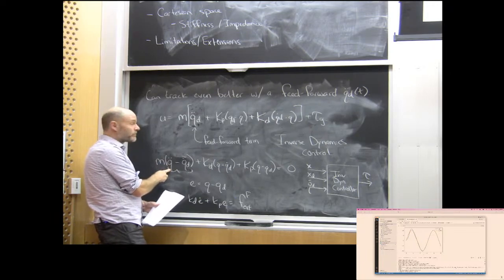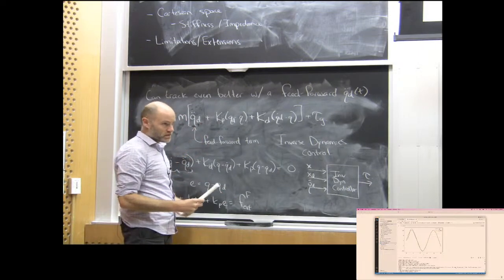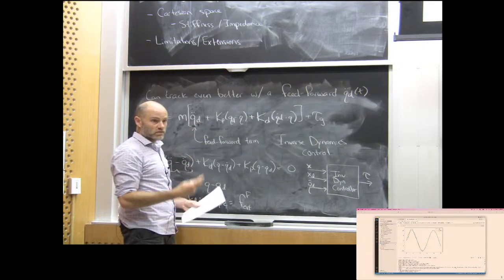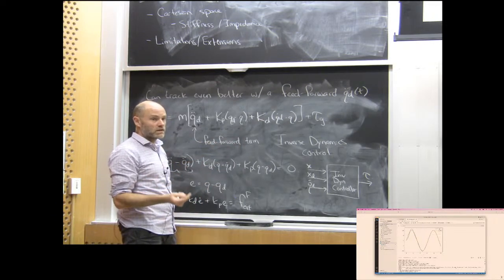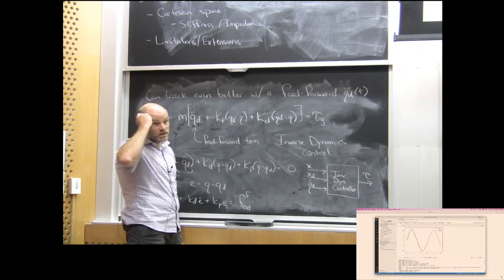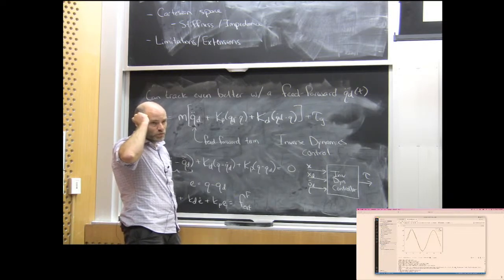What about Q dot? For Q dot, depending on the sensors, there are rotary encoders there. We typically think of positions and derivatives as pretty clean, and we try to avoid accelerations as a general rule of thumb. You don't want to do high bandwidth control with accelerations.